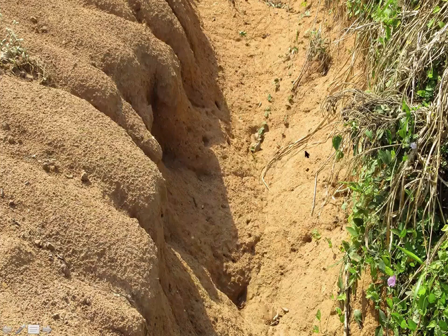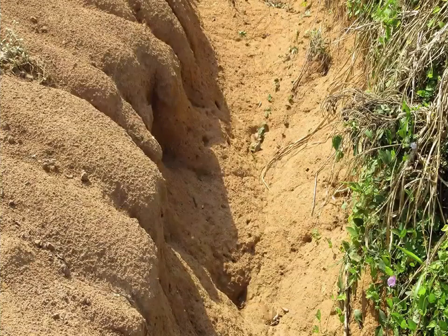So the widening of this area increases the surface area. Hence, the river would receive greater solar radiation, and so the temperature of the water body would also be higher. Streamside erosion may also remove vegetation cover along the streams, further exposing the water to the sun's thermal radiation.